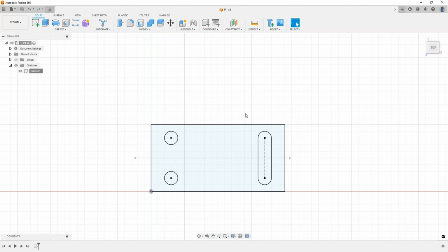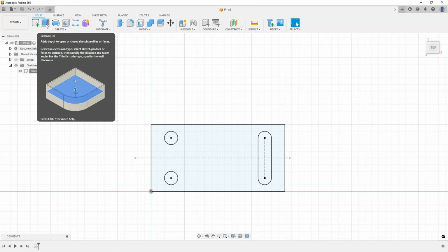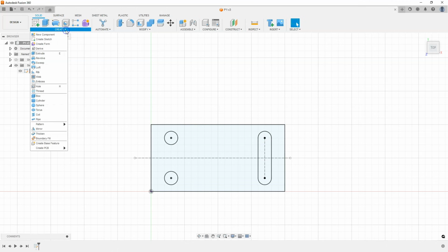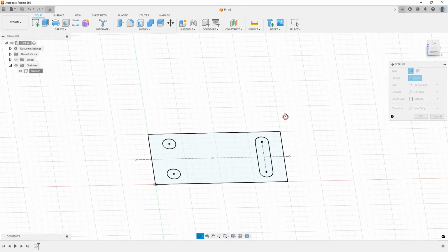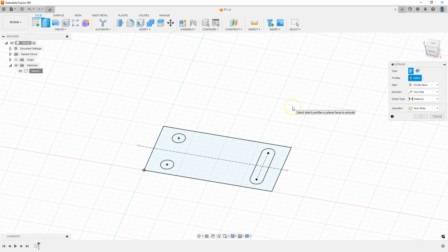We can use sketches to get a solid based on the sketch, and to create a 3D model based on a 2D sketch, select Extrude Operation. You can click this icon, or from Create menu select Extrude. And after selecting the command, the selection of profiles to be extruded is active. The field highlighted in blue means that the selection of the feature with this field is active, and by pressing the mouse wheel you can slightly rotate the view to make it easier to select the geometry and select a profile based on which a 3D solid will be created.